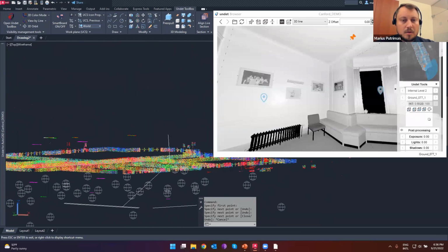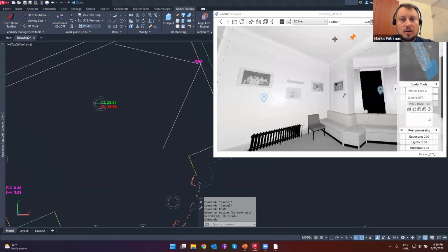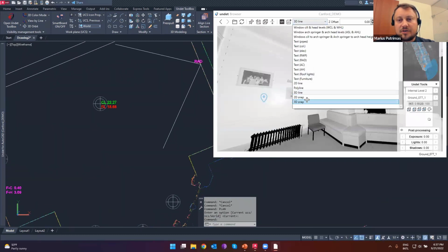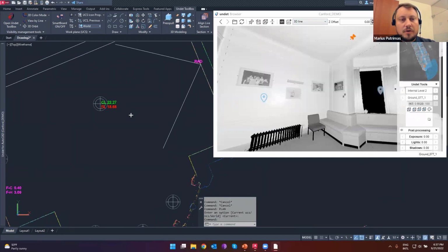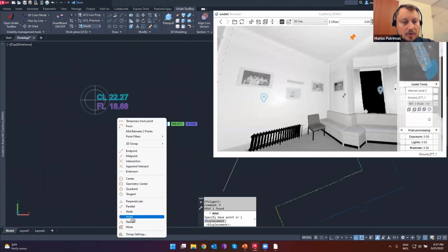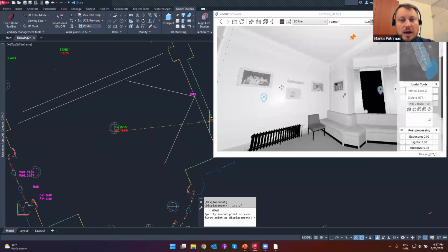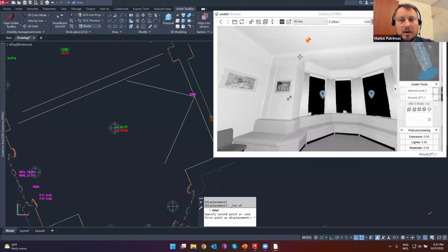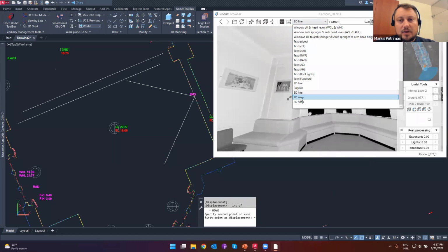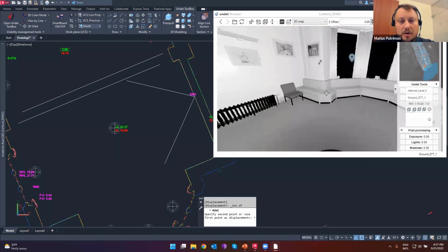Okay, so our scripts also work with Undet for AutoCAD, where there are 2D and 3D snap. For example, you select this object, press move, select, I don't know, the insert point. And you see, now I can move. I go inside Undet Browser, select 2D snap or 3D snap, and just click over here.